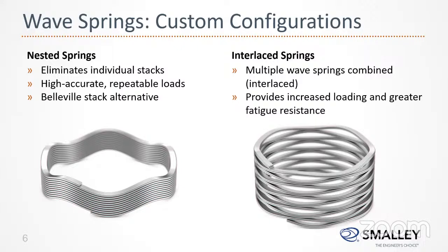Another technique to achieve higher loads is by interlaced springs. Normally crest-to-crest springs are all manufactured with a single turn, but here you can see there are 2 wires. We can even manufacture with 3 wires and 4 wires. So without increasing the height, we can increase the load 2, 3, or 4 times more. So this provides increased loading and greater fatigue resistance.